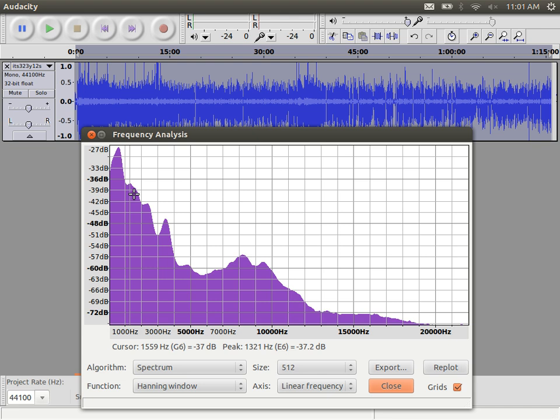So most of the signal is concentrated in this area, from 0 hertz up to maybe 2000, 3000, 4000 hertz. When people talk, the frequencies they generate usually range from 0 up to 4000 hertz. And that's demonstrated here: from my lecture over that period of time, most of the components were from 0 up to 3000, 4000 hertz.